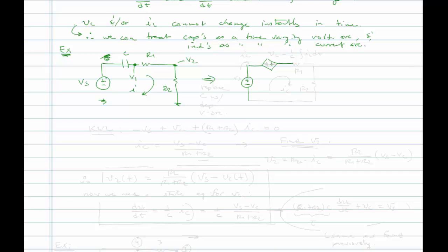And I think I did it backwards. It's a plus and a minus here, okay? I wanted to do it that way. I did that because of the current direction, okay? IC is going this way. And we have our two resistors, R1 and R2. And we will call this VC, and VC is equal to 1 over C, the integral of the current IC. Okay?